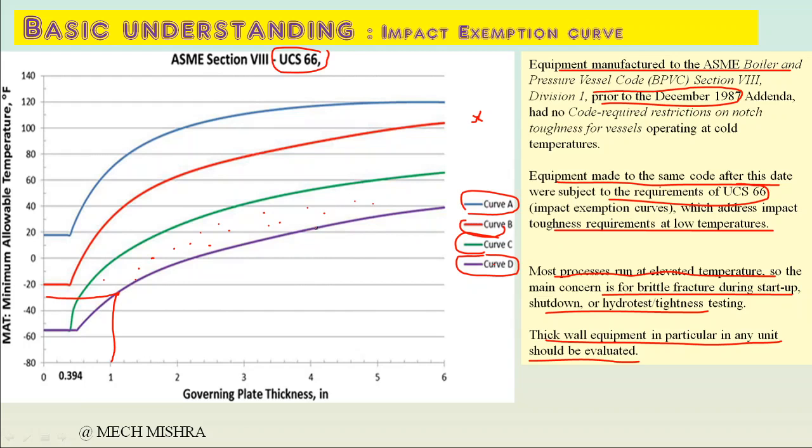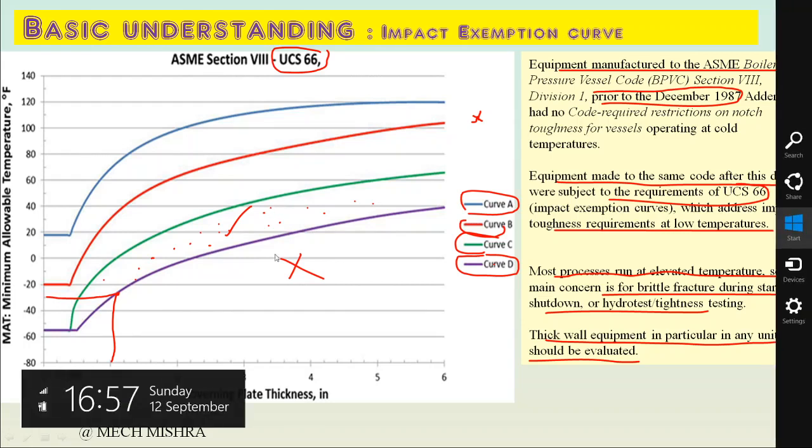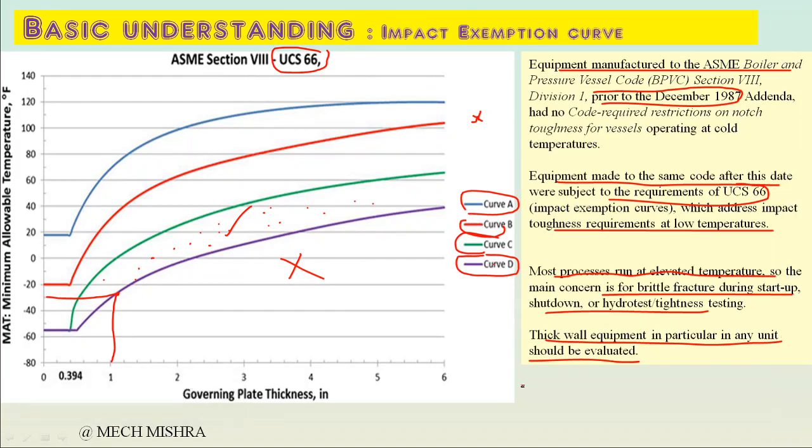Okay, so if I am below this curve, impact testing is not required. If I am above this curve, impact testing is required. So that's how we need to check: if I am operating at lower temperatures, my material should be impact tested to confirm whether there is a chance of brittle fracture.